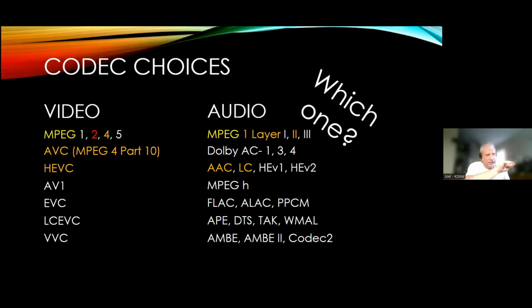It's kind of like Moore's law. It really spiked over the last 5 years. And so they're getting to the point where they can send intelligent voice speech, you and me talking, and I can understand it's you and you can understand it's me. We're getting to the point where we can have bit streams at 2.5 kilobits per second, and it's completely understandable. It doesn't sound like a robot. But for broadcast quality, you need a higher bit rate. The lowest we use is probably 16 kilobits, but that's so you can do music and stuff like that. It renders better when you have more bits, but it's a very specialized field just to do audio.